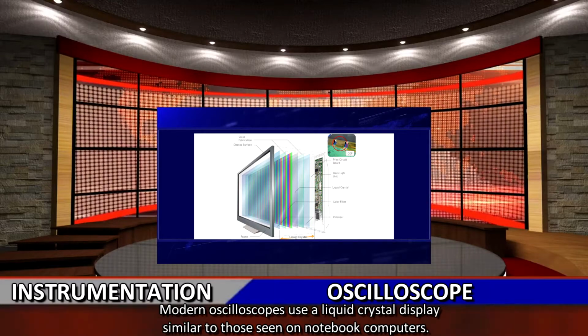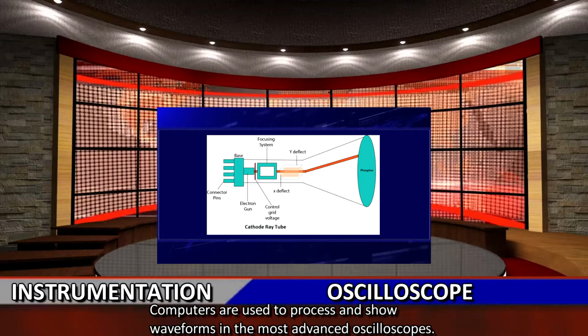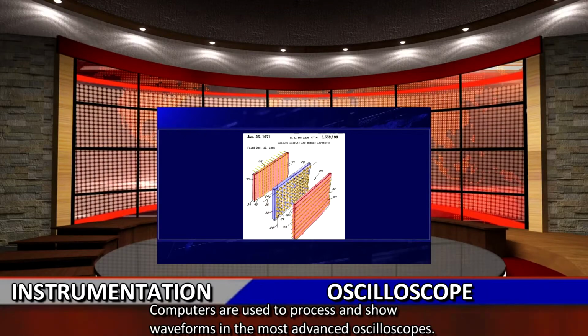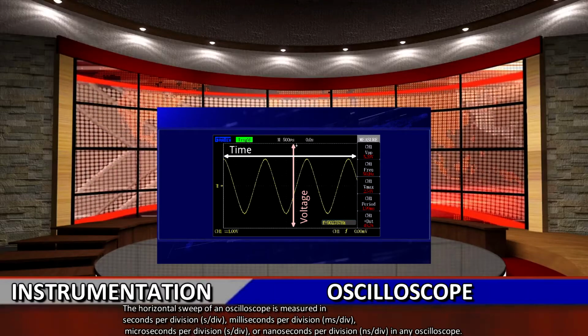So computers are used to process and show waveforms in the most advanced oscilloscopes. Any sort of display, including cathode ray tube, LCD, and gas plasma, can be used in these computers. The horizontal sweep of an oscilloscope is measured in seconds per division, milliseconds per division, microseconds per division, or nanoseconds per division.